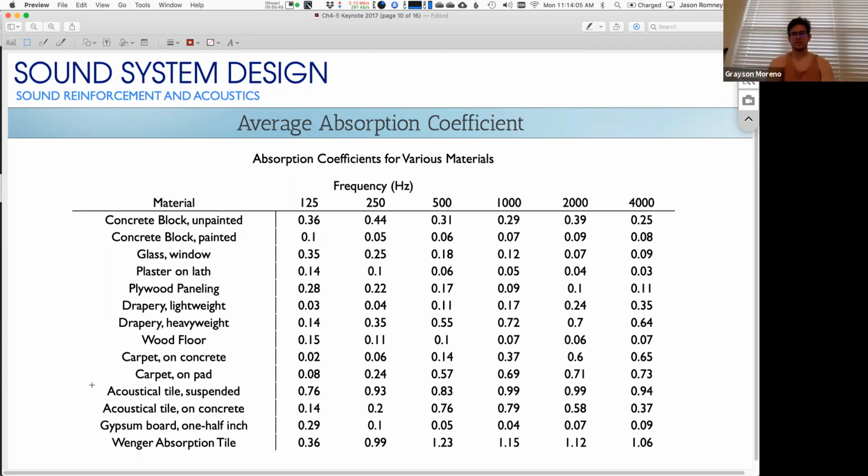Yeah. So my second question is, I know that the size of whatever is absorbing is going to depend on what frequencies come in and out. What about the air gap? Is there a certain set standard size? Yeah, not really. But generally, the bigger the gap, the better, because you can leverage inverse square law as much as possible. That sound gets quieter the farther it has to travel before it comes back through the tile.